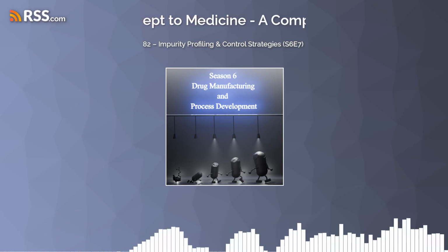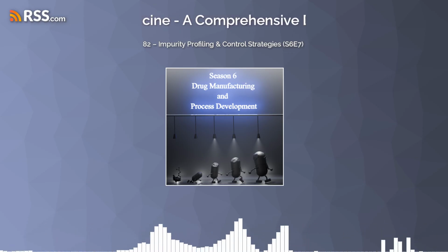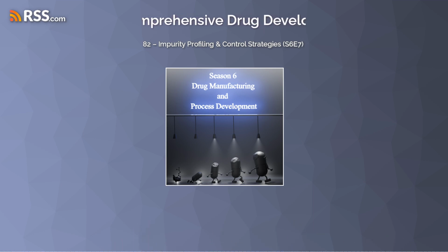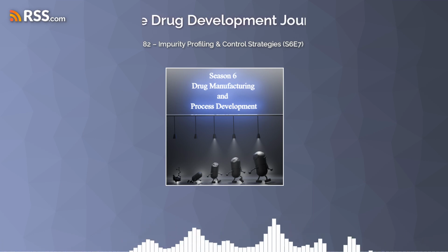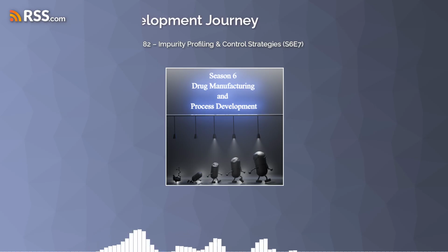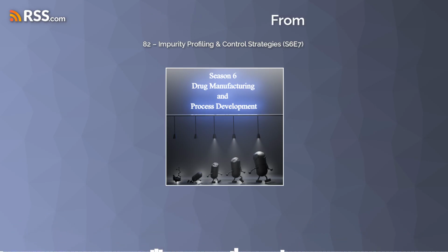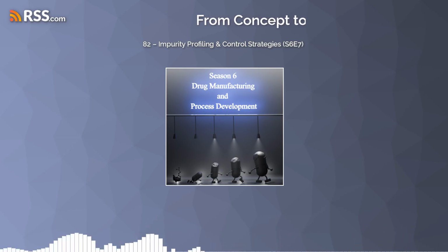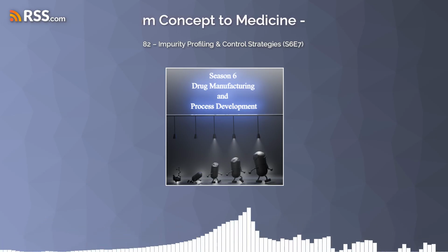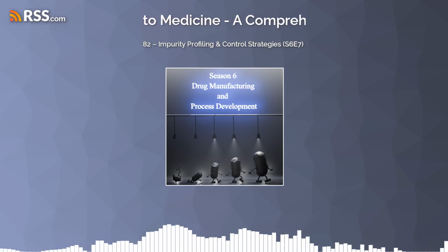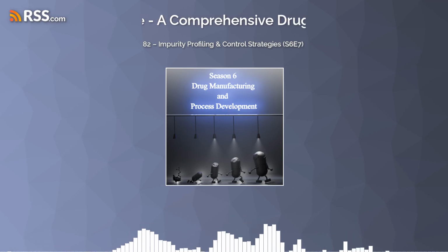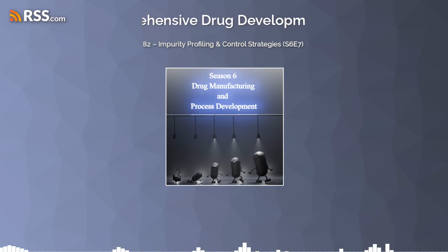Pretty much. Activated carbon, like charcoal, is a common one. It just absorbs a bunch of stuff. But they also use more specific chemicals like TMT or L-cysteine, which is an amino acid. TMT being... Oh, right. Sorry, 2,4,6-trimercaptotriazine. That's a mouthful. Tell me about it. But anyway, the interesting thing they talked about was using L-cysteine because it could avoid having to do another filtration step to get rid of the activated carbon.